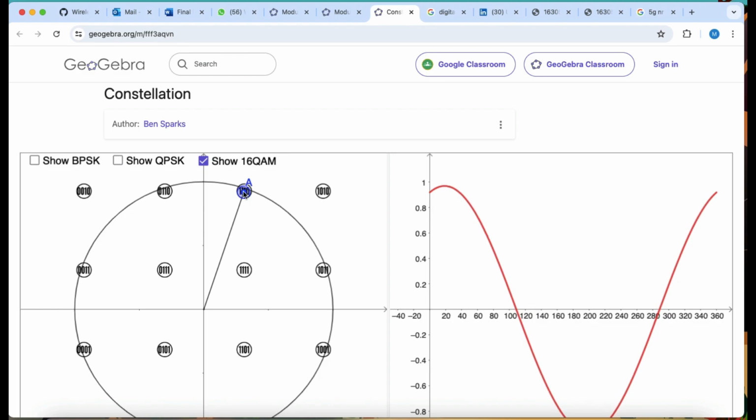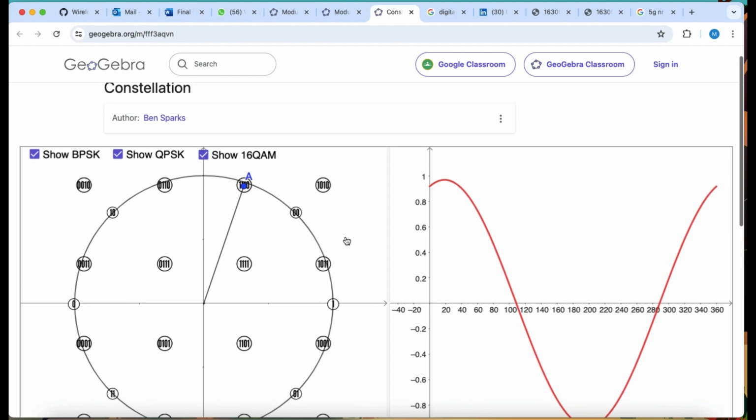If you're close to a base station, you're going to transmit higher data, you're going to use higher modulation schemes, so you'll get higher data rates. Since you're close to your base station, it's less likely that noise will corrupt your signal. If you're away from your base station, due to Rayleigh fading and different fading components, you're most likely to get corrupted. Your data is most likely to get corrupted by noise. That's why they try to use lower modulation schemes like QPSK and BPSK. So that's the idea behind these modulation schemes.